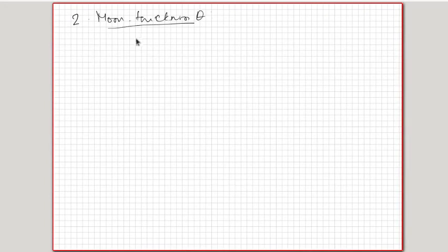Since the mass flow rate is rho u dy, and if it is carrying momentum at free stream velocity, this is multiplied by u infinity.